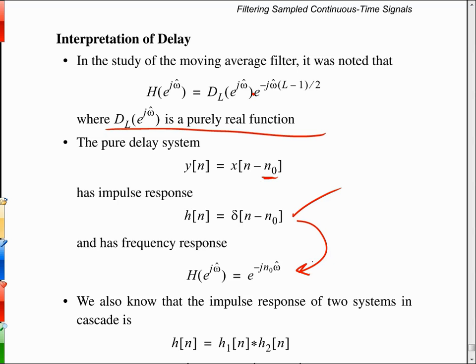Remember the first part of the lab last week, you put in a signal which you delayed by 4 samples, right? And then you had this moving average filter, and how many taps did that moving average filter have? Anybody remember? Well, the second part did. In the very beginning, though, how many taps? I was thinking it was 9. It's 9, right? It was 9 total taps.